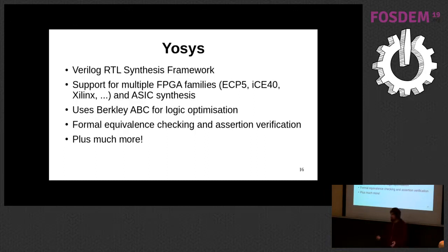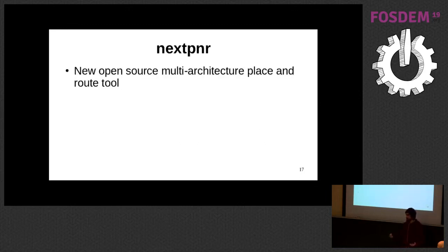So that gets you from your Verilog to a netlist, a connection of all FPGA primitives, so LUTs, flip-flops, but it doesn't actually tell you how they would fit together on the device. So that's for the place and route tool to deal with. For that we have nextpnr.